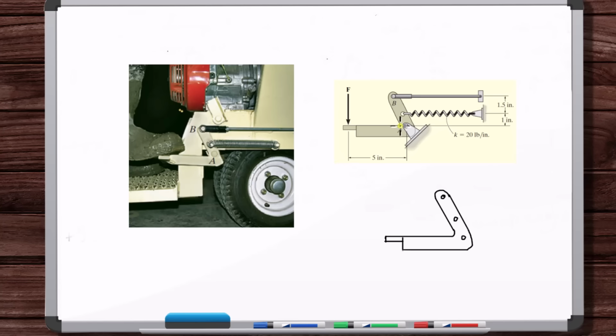Okay, for example, here, in this problem, they give the stretch of the spring. They tell you that the spring is stretched, and they tell you about how much. So because they tell us that the spring is stretched, we know that the spring is pulling in this direction. I mean, they could say that the spring has been extended by this amount, but maybe the spring started in compression and it's still in compression, so it's still pushing back.